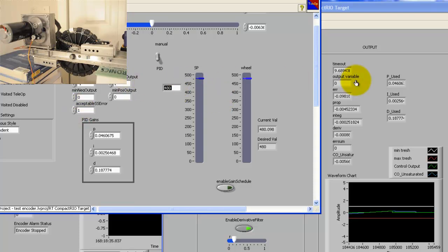Let's just do 470, 450. So that wasn't too bad. I just want to gain more room up at the top spectrum. So if I did a couple of inches, 260. It also performs very well at the low spectrum too. So that's just one thing to make sure when you're looking at your controller. Your gains for large swings also accommodate for small error changes as well.